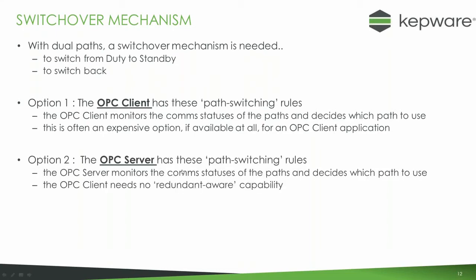So the second option is to put it in the OPC server. So the OPC server must monitor the COM status of the paths and decide which path to use at that particular time. The advantage of that is the client or clients need no redundant aware capability. They're not doing the switching. The KEPServer itself will be doing the switching.